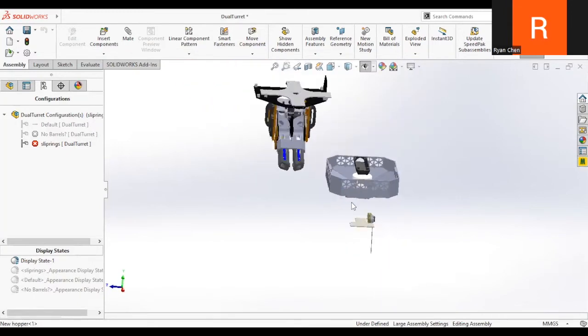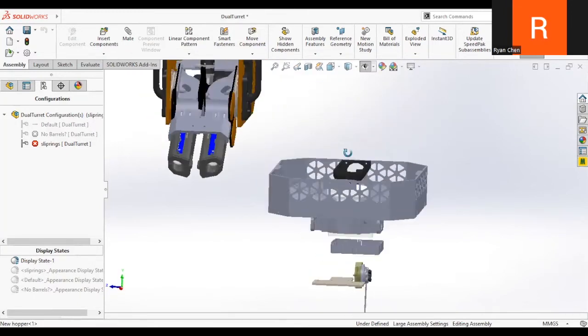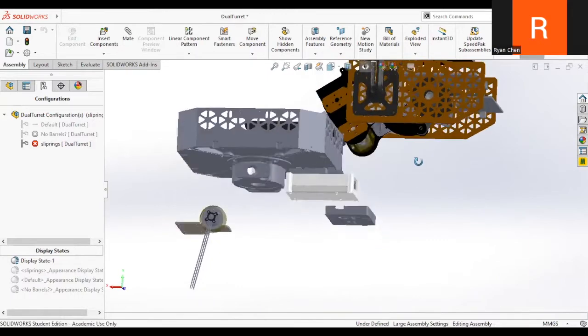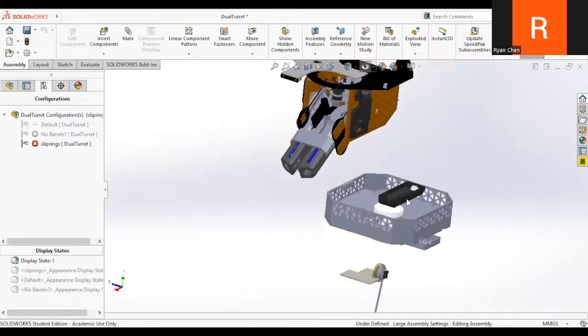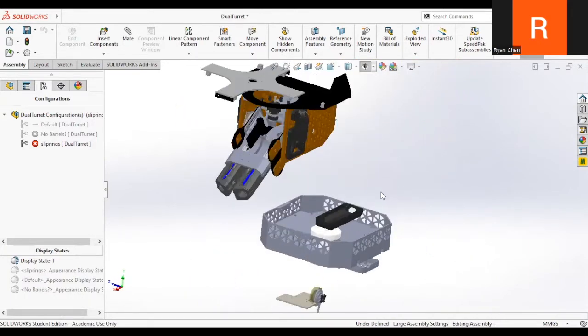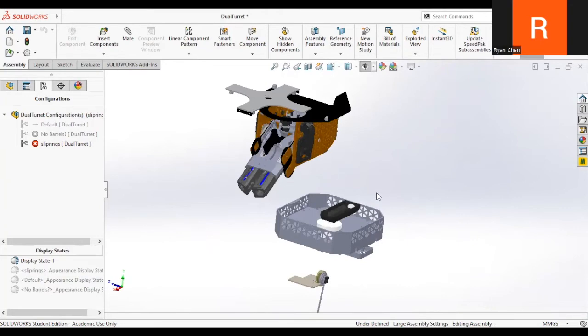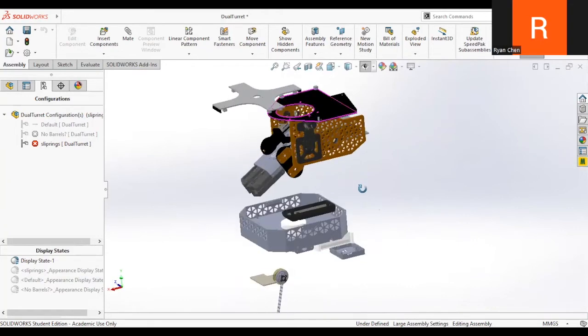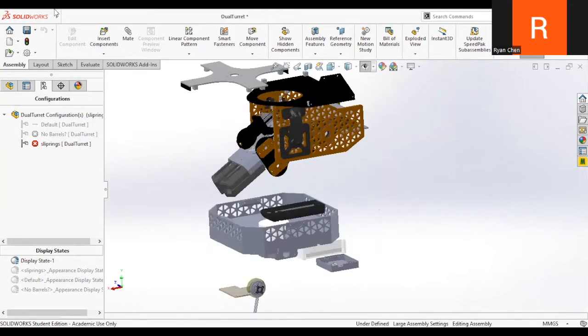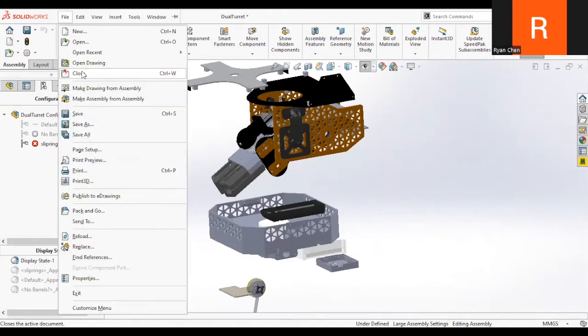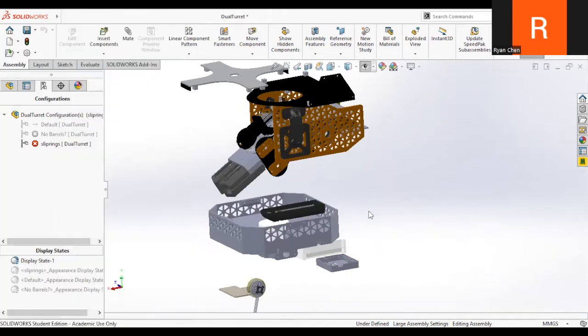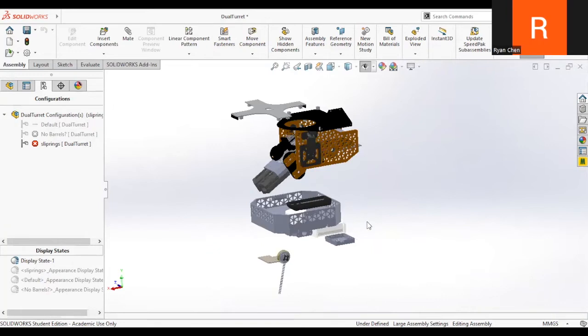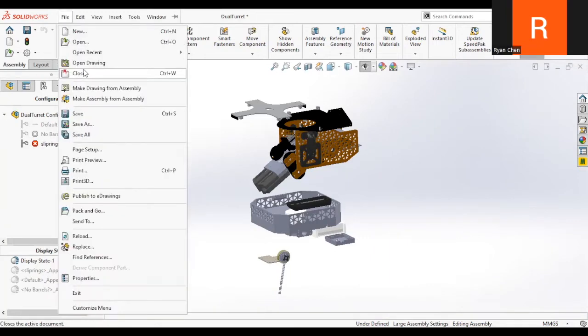So as you see, there's a different design. You see stuff moves. I'm pretty sure the person who was working on this, who I believe is our Sentry lead, used to be Theo, then Aiden, and now it is Richard. So they're no longer working on this stuff. But yeah, the hard thing while working with assembly configurations is that some of the mates might stay the same, so you have to suppress a lot of the mates, or else you get errors super easily. Let me just close this.